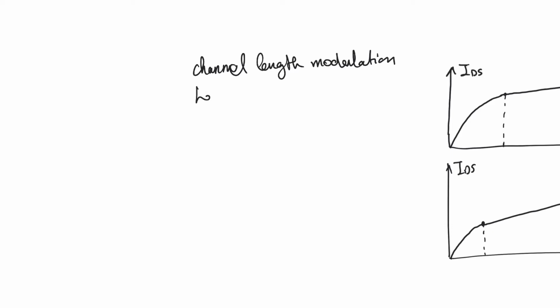First of all, less saturation current, because the current is increasing linearly with VGS, and definitely the velocity saturation current is lower than the corresponding pinch-off saturation current. But more importantly, perhaps, we have early onset of saturation. So the voltage at which saturation occurs is earlier if velocity saturation is the dominant mechanism.